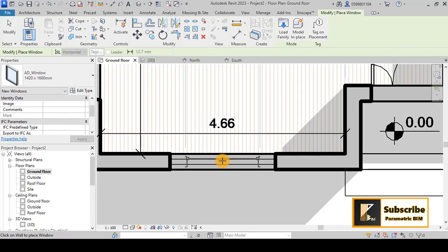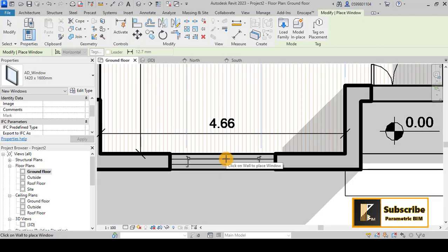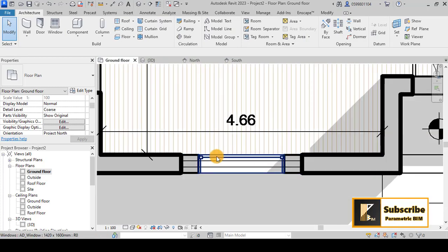So once I choose, as you see, the window is hosted in a wall. So I will click here. Maybe you can have the opportunity to make it recessed or flush as you want, so that the sill of the window will be inside in that way and outside in that way. So I will choose something like that.